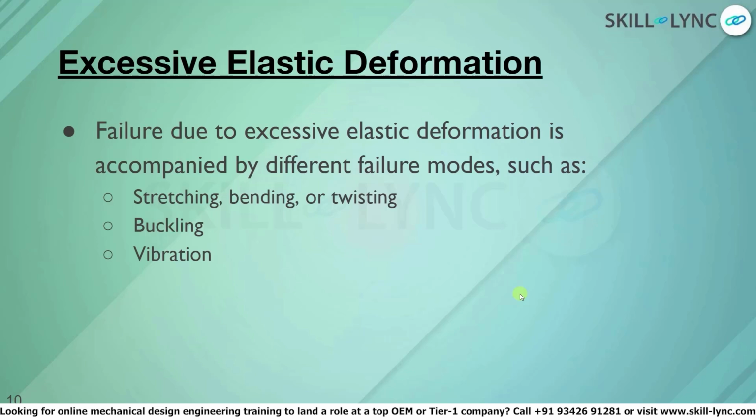The next type of failure is vibration. This is a dynamic property, and in any material or material system, or you can call it a structural system, there will be vibration due to whatever load it is undergoing. Normally, vibration is acceptable as an inevitable phenomenon, but when it reaches resonance or when there is an excessive amount of vibration, then even when the load the material undergoes is within the elastic limit, it can still attain failure.